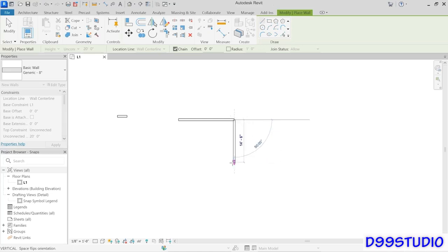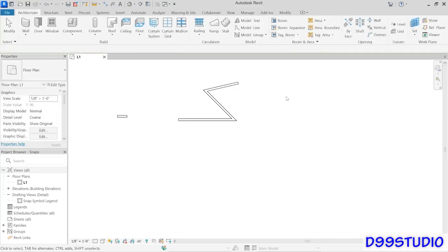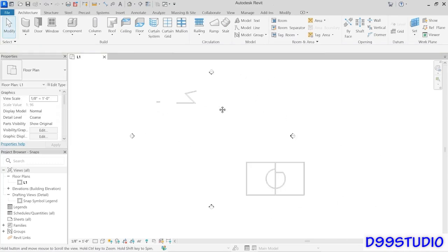45 degrees, 90 degrees, horizontal and vertical, right? So you can snap to any of those preset increments just by clicking when you see that little indicator on screen, or knowing that even if you're going at some random angle, you're never at a fractional degree, you're always at a whole degree increment. Right? So those are the increment snaps. Those are nice because if you set them to a value that you want as your minimal, then you know that even if you eyeball something, it's going to be within that tolerance.